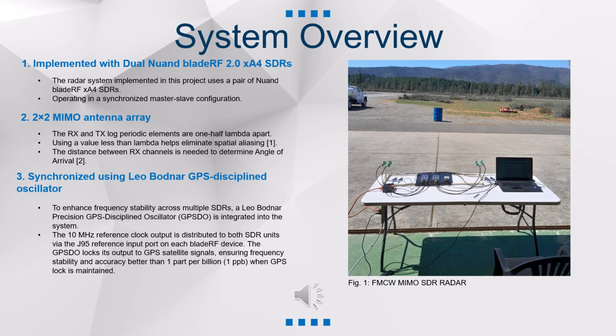The use of a 2x2 array allows for spatial diversity, which is necessary for determining the angle of arrival. Although this project is capable of determining the angle of arrival using the MUSIC algorithm, this report only covers range estimations in the time and frequency domain. A separate advantage to using multiple antennas is it simply directs and detects more of the signal.